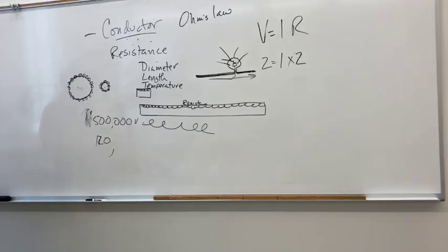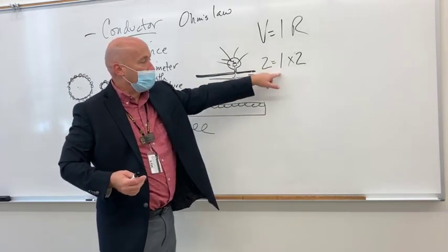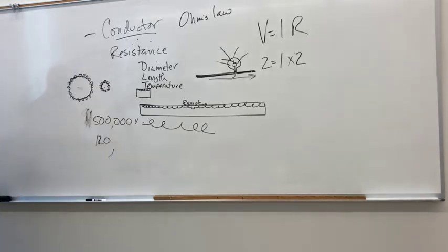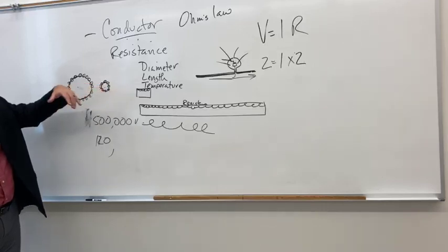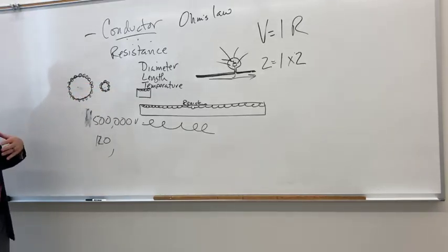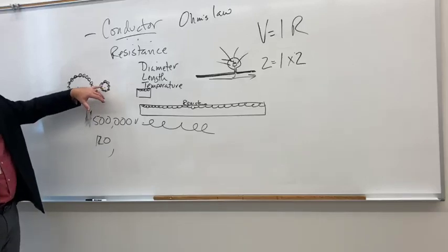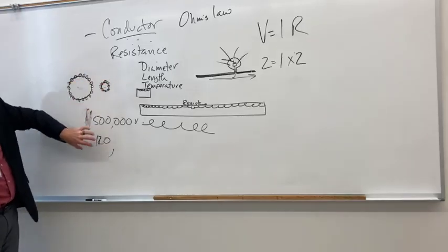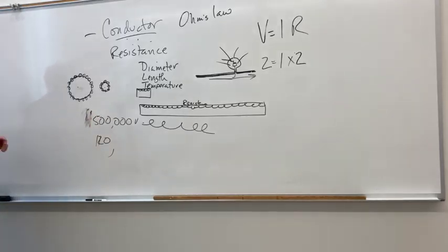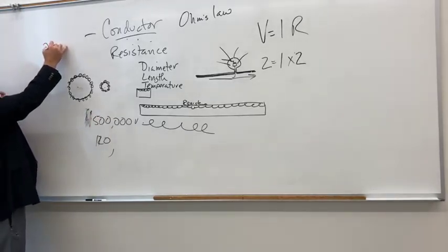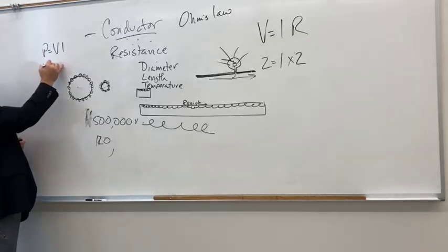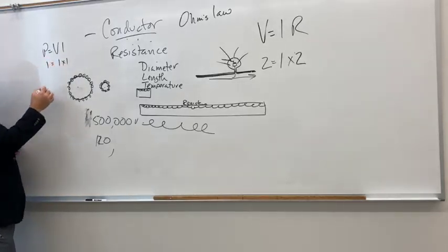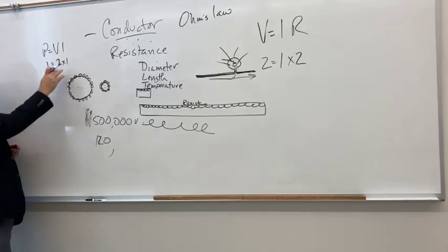So if we can substitute voltage for amperage, then essentially we can use a smaller wire, which is going to have higher resistance, but using higher voltage and lower amperage to deliver that same amount of power. Because electric power is equal to voltage times intensity. Okay? So, voltage times intensity, again, we've got 1 equals 1 times 1, and if we double our voltage, what can we do with our amperage?